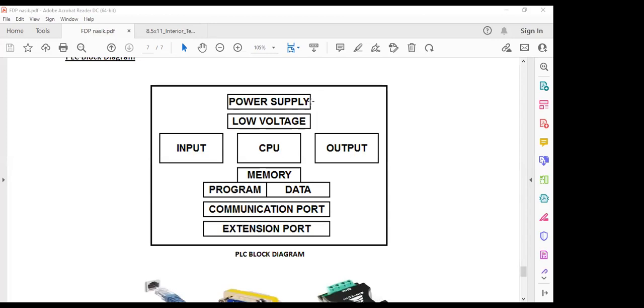You need to answer and you have to text it in chat box. What about DC power supply? And let me tell you, in industrial automation, DC voltage we use 24. So 24 volt DC will be used when you have PLC. So if you have to power on PLC with DC power supply, you have to provide 24 volt DC. In microcontroller, standard voltage will be 5 volt DC. So you need to tell me and answer it fast, please. What is the source of 24 volt DC?